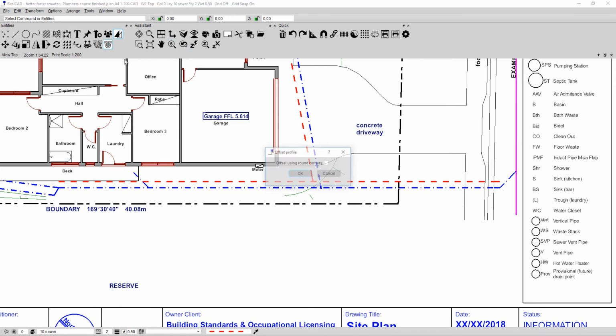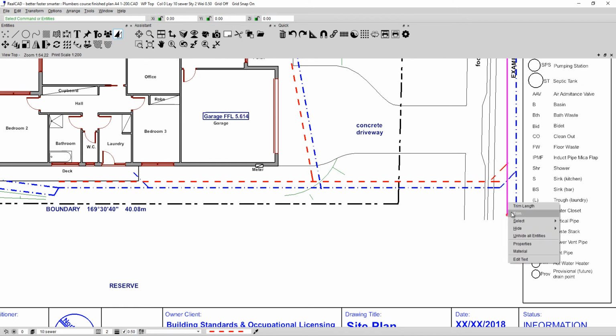I'm going to do the same with this line. Make a duplicate copy and place that out in the street a little bit closer. So there's my red line, and I'll repeat that for this one as well. Take that line and make a duplicate copy just over here, and I'll pop it about there. Then all I've got to do, right click out, right click on the edge, trim to this line, trim this one to this line, and oh, in fact no, this line shouldn't trim, this one actually does come past, it's out in the street, comes back out, so I've redone that length there.